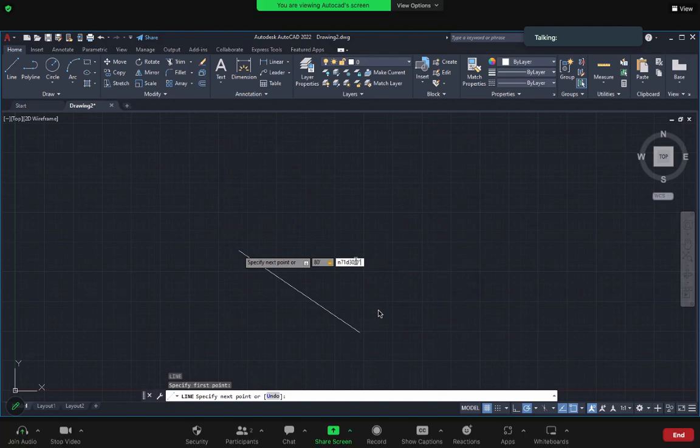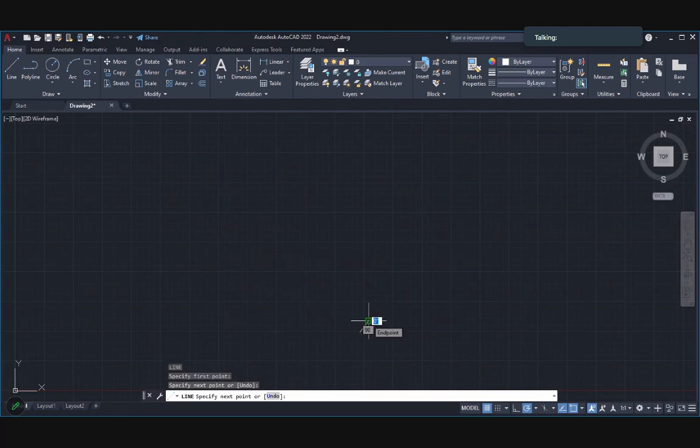Let me get out of here. Let's still put in north 71 degrees. I moved my mouse, so I'm sorry, I have to repeat that again. Okay, so I'm going to put in 80 feet. If I move my mouse, what's going to happen is the computer or AutoCAD will think that I wanted to pick. So it's going to put here north 71 degrees 30 minutes and 0 seconds west.